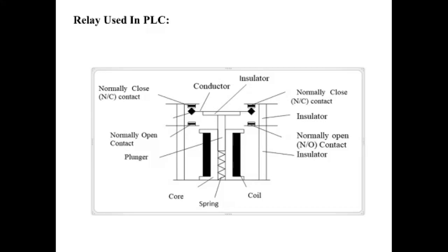When the coil is energized, the internal timer in the relay begins running. When the timer value reaches the preset value, the relay energizes. When this happens, all normally open contacts on the relay close and all normally closed contacts on the relay open. Also notice that when the power is removed from the relay coil, the contacts immediately return to their de-energized state, the timer is reset, and the relay is ready to begin timing again the next time power is applied.